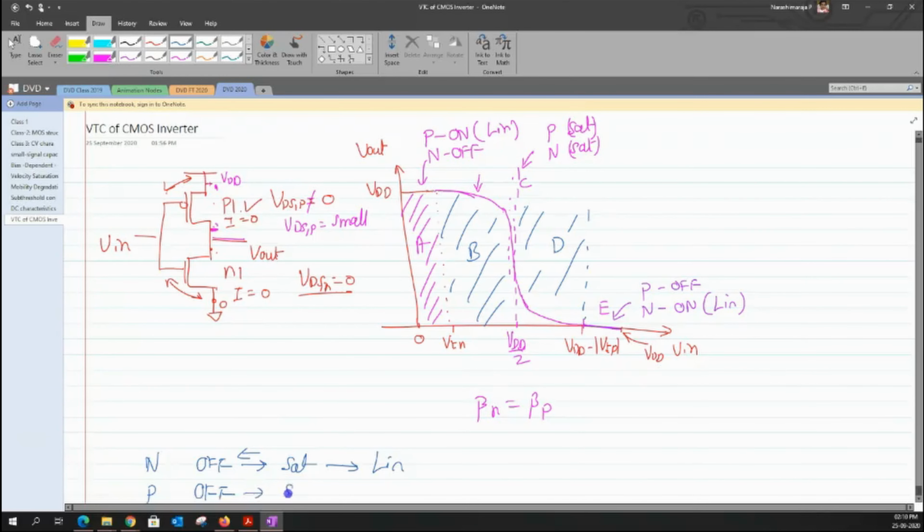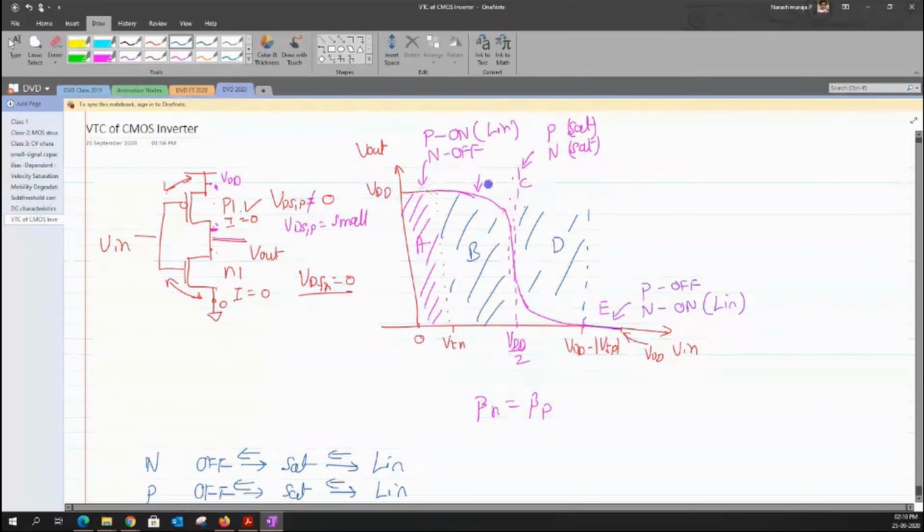The path only exists which can flow something like this. Since only this particular path is always valid, from the off, the NMOS, when it gets turned on, moves into the saturation region. But the PMOS would still be in the linear region because it has to conduct very little current. Even though it is capable of conducting a very large current, it has to conduct very little, due to which the VDS of our PMOS would be less negative than the negative value of VOV of the PMOS transistor, okay? So it would be in the linear region, okay?